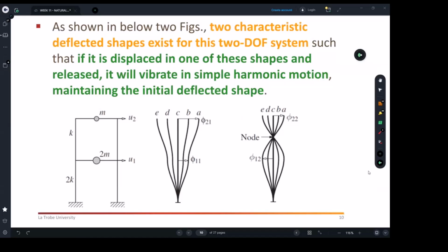So in other words, why we're learning this week, why we need to find the mode shapes. Basically, because it will give you the most adverse deformation a building can be experiencing. We're trying to find the mode shapes because they will help you to calculate the time period for the building when it's vibrating at such a mode, and that will give you the most adverse effect.